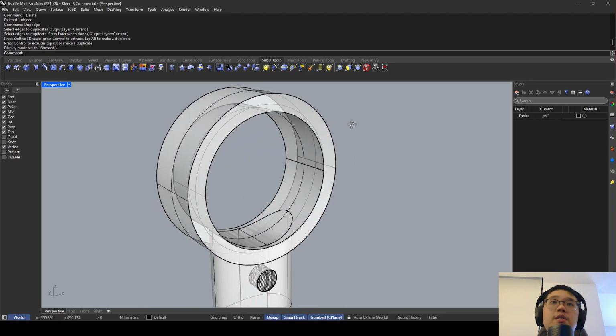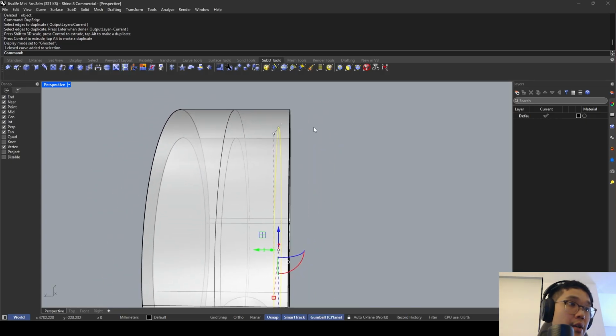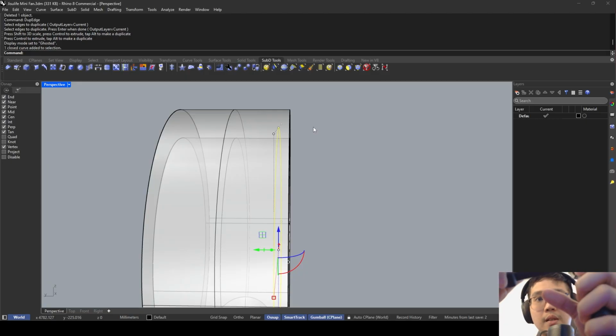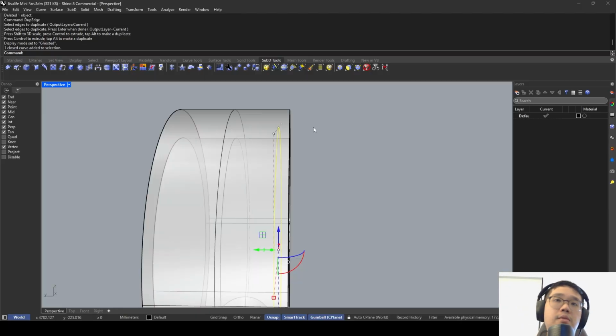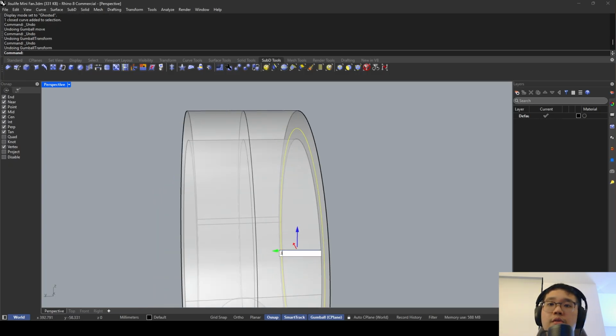Go to ghosted. So that's what I have right now. So it actually steps in by roughly 3 to 4 mil. So I'll just bring this minus 3 mil. Just do 3 mil.